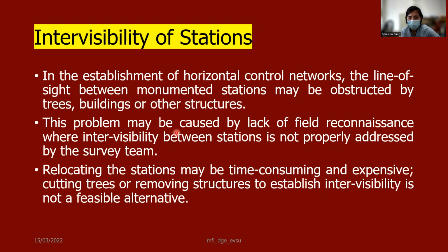The problem may be caused by a lack of field reconnaissance. Since for your activity you only refer to the overview, you don't really see on the ground whether the line of sight is clear enough to observe the other points. That is one reason why it needs ocular inspection, actually looking on the ground whether the other points are visible. And relocating the stations may be time consuming.